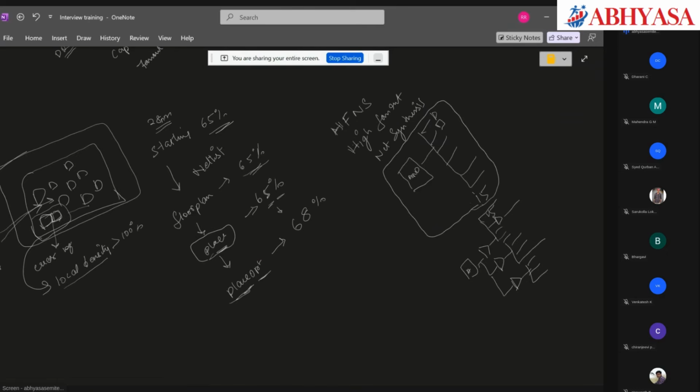Now I have added, for example, 3 buffers. My AND gate output will be connected to 3 buffers, preferably big size, which means 8x or 10x. And each buffer in turn will drive 5 cells, so that my single gate is not overloaded by 15 fan out. It is now broken down into 3 pieces. This is high fan out net synthesis.